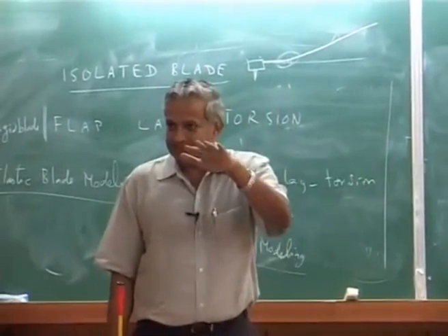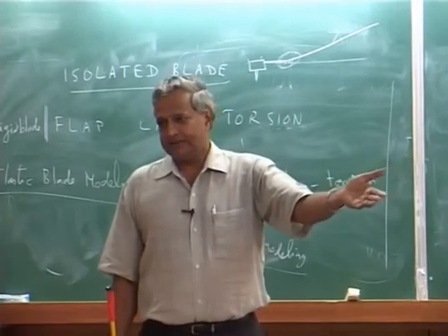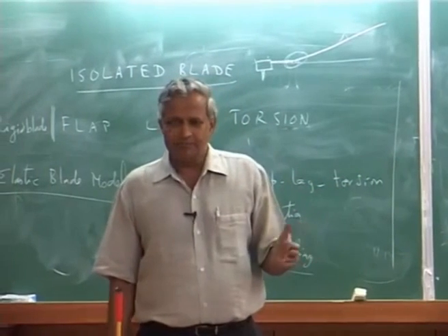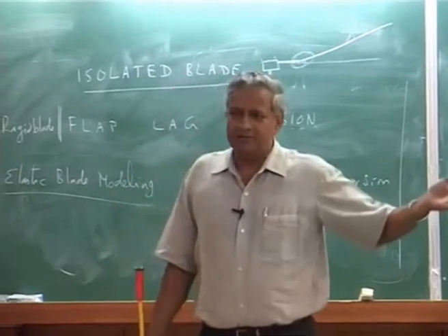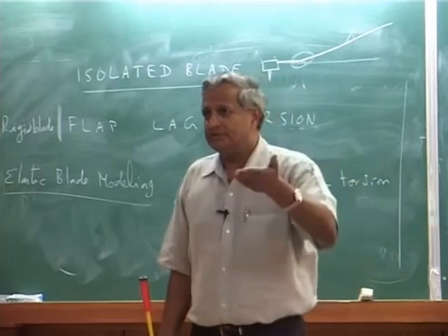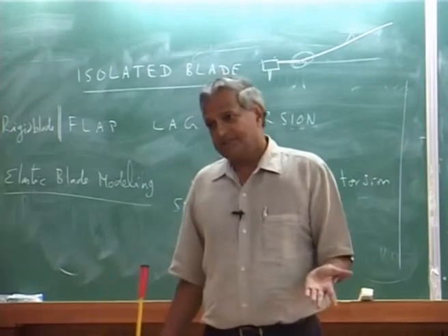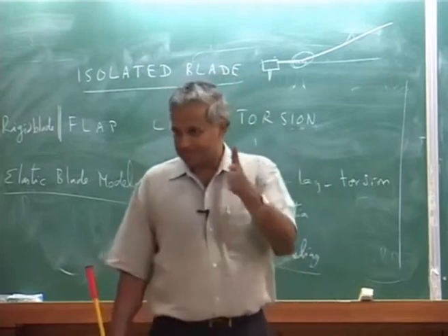Mean value and then vibration. Mean is usually not tremendously large, because you take 4,000 kg helicopter, that means 10,000 Newton for 4 blades. That is the mean value in the shear.